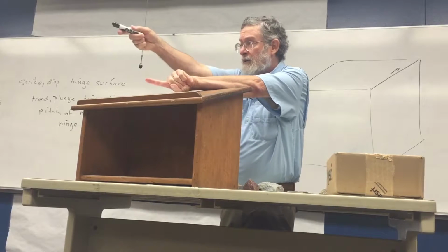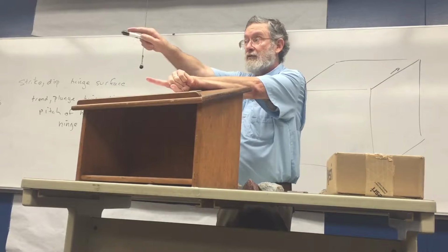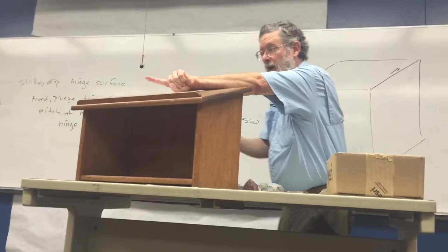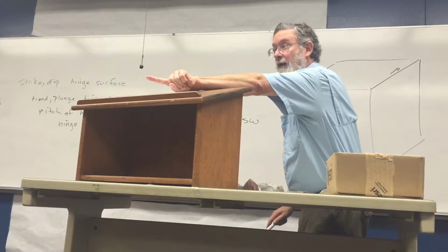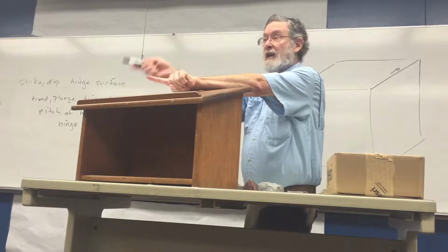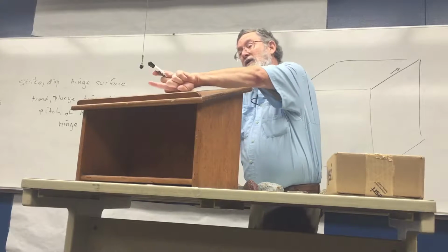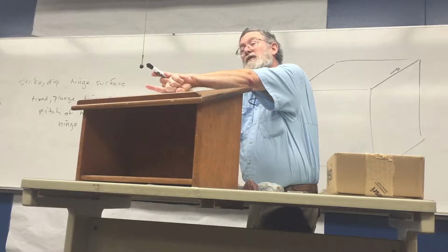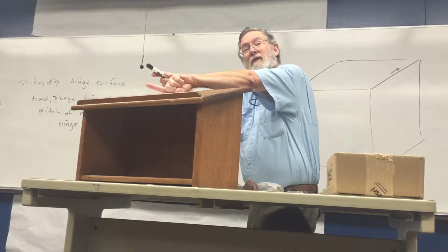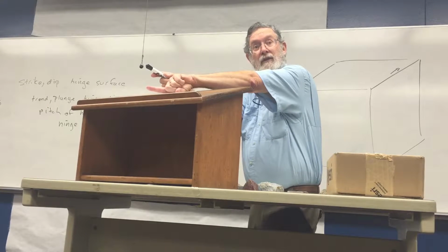We talk about the direction in which the line is going down. That's our trend. And so right now my trend is right towards Sam. So we have here an orientation that looks like it's going to be about 210. We talk about the plunge, which is this vertical angle here, which would be probably 12 degrees in this case.